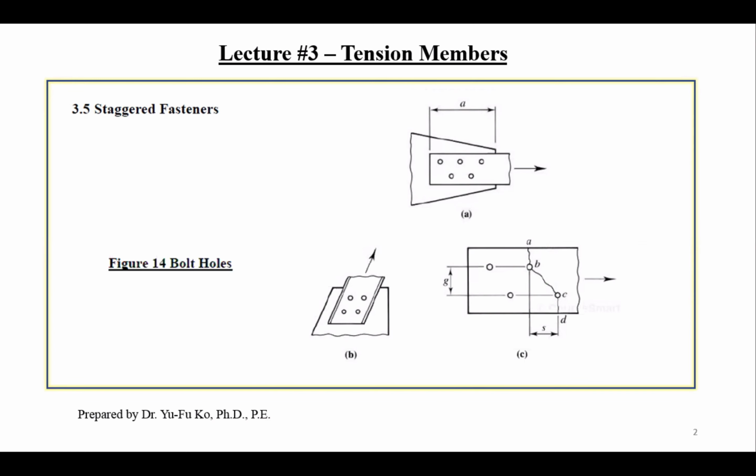Okay, thank you. So the only benefit I would say is to fit the limited spacing in the connection. That's the only benefit. There's nothing really beneficial about doing this. It creates a lot of problems for the designer to do the calculation and to control the behavior of the connection and the member. Okay?